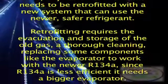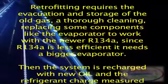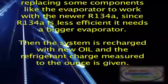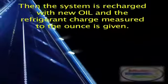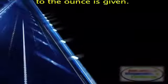Retrofitting requires the evacuation and storage of the old gas, a thorough cleaning, replacing some components like the evaporator to work with the newer R134A. Since R134A is less efficient, it needs a bigger evaporator. Then the system is recharged with new oil and the refrigerant charge, measured to the ounce, is given.